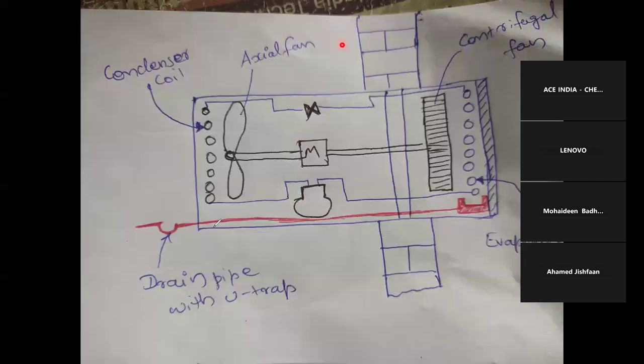So in your homes, you can see this now. Some kind of supports will be there, isn't it? Some kind of supports which hold the backside of the machine this way, isn't it? So this is how the window AC supports look. And this back portion should always be in contact with the atmosphere itself. That's how the heat exchange takes place between the atmospheric air and the condenser coil. Then, after a subcooling process, it is converted to high pressure liquid. And this high pressure liquid is passed over to the expansion valve, or the throttling device.